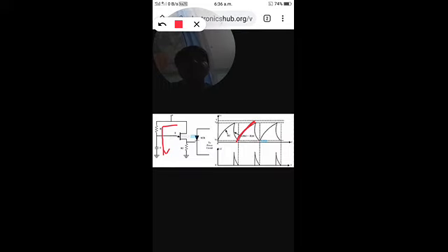When the UJT is conducting, in a short duration of time, that is when the capacitor is discharging, it acts as a short circuit path for the capacitor. So the current flowing through the resistor will produce pulses. These pulses act as gate triggering pulses that are applied to the SCR.